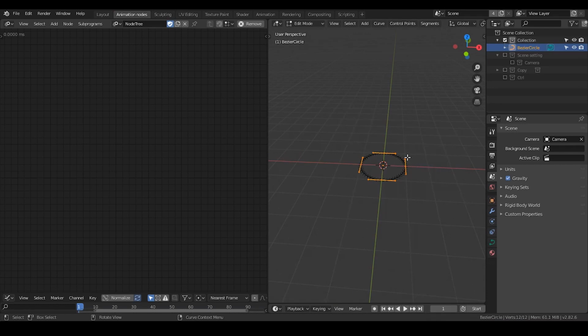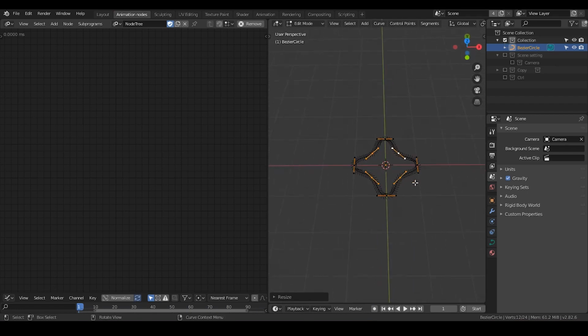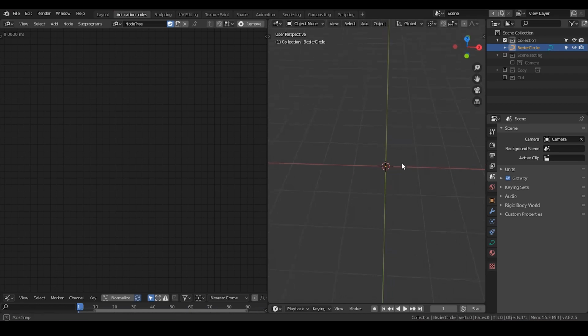So we can create a circle. Now we have 4 vertices, and we can try to divide that. I'm going to select each second and drag them to the middle. Obviously, you can increase the subdivision and drag them to the middle so that it becomes more like a star shape, and so on and so forth. This, however, is not procedural, and I have to select each second vertex each time, this is chaotic. So I'm going to do a procedural star shape. So let's do that very quick.